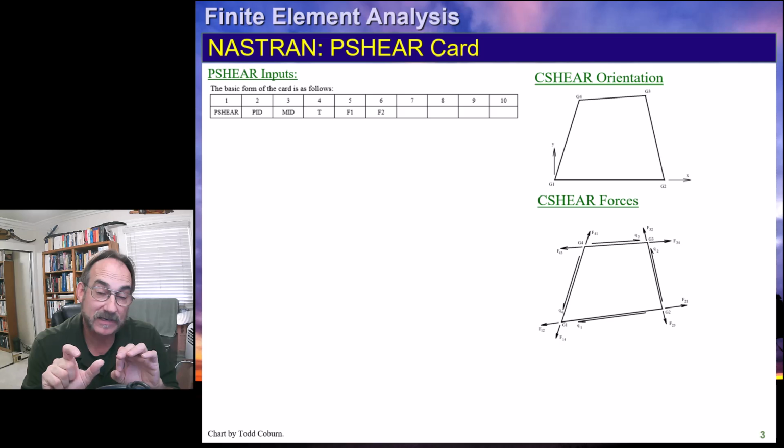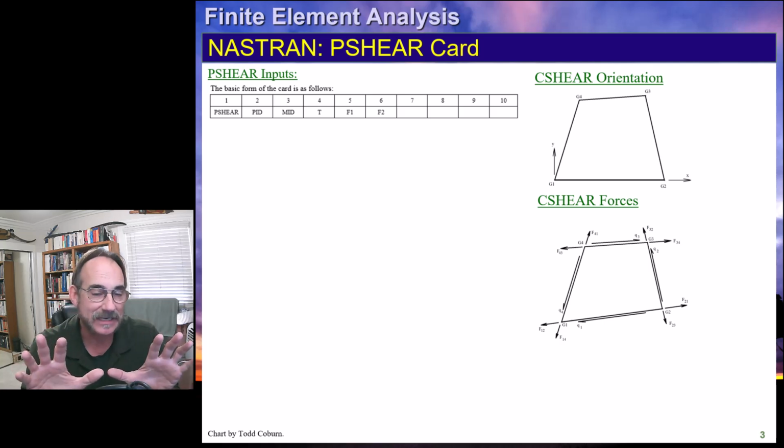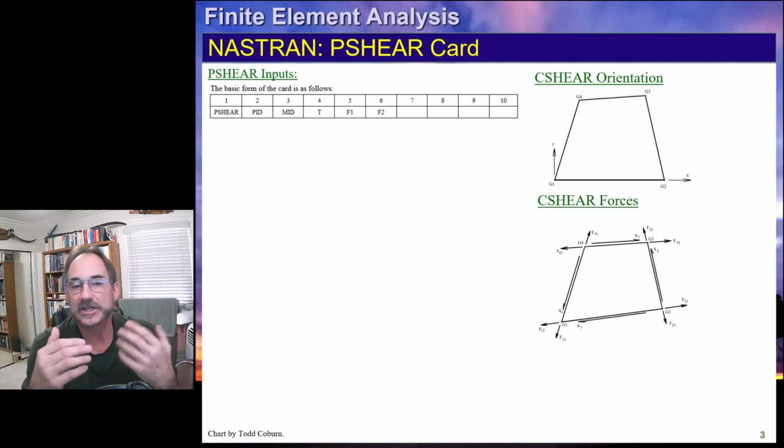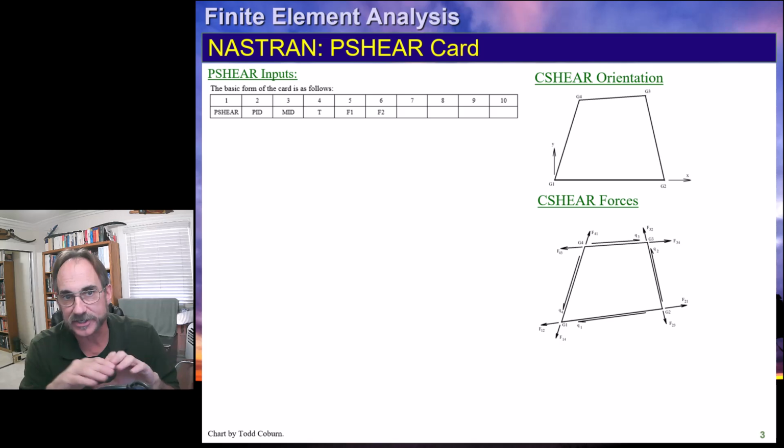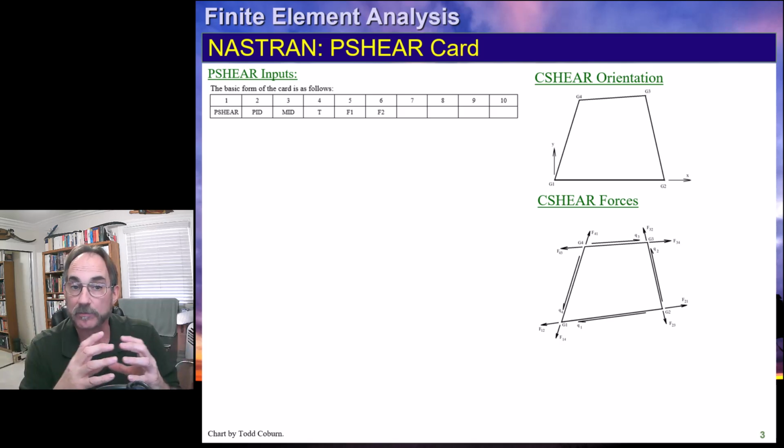We define an effective width of skin that we lump in with the stringer to give a better analysis. This is commonly done with compression. Actually, shear lag can also cause us to use less than effective skins for structures in tension and such.